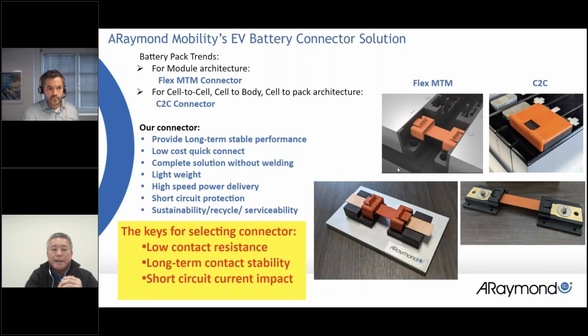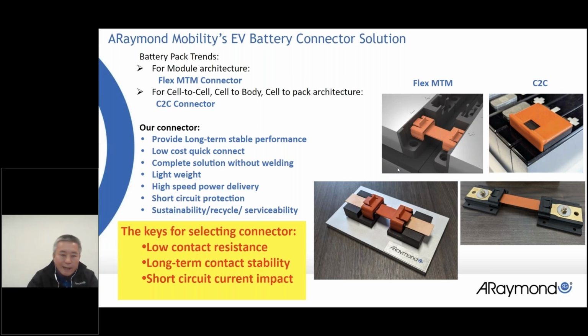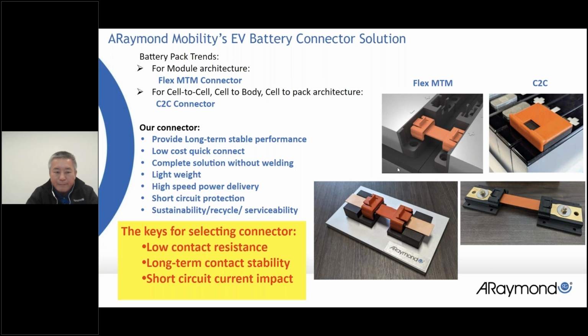As I said, at ARaymond Mobility Group we have an EV battery connector solution which covers most of the battery pack trends right now. We know the current battery trend is either the module architecture, or cell to cell, or cell to body, or cell to pack solution. For the module architecture, we have a flex MTM, which builds the flexible bus bar inside without welding. We also have a cell to cell connector to connect your cells without welding.